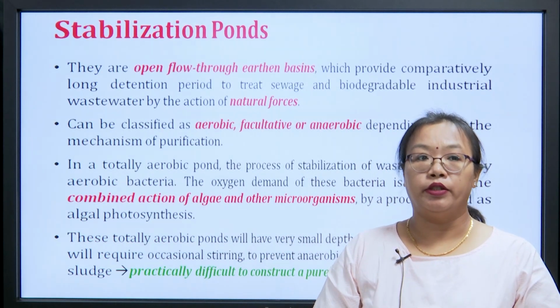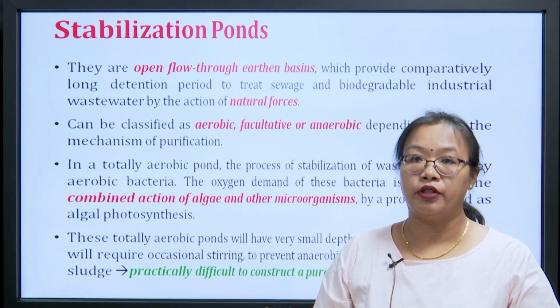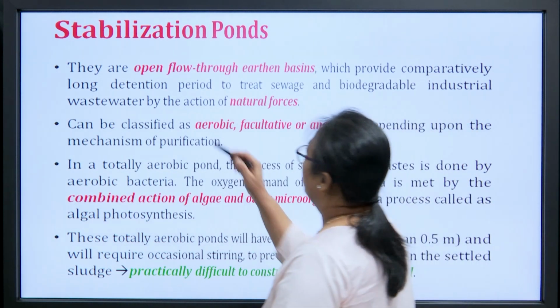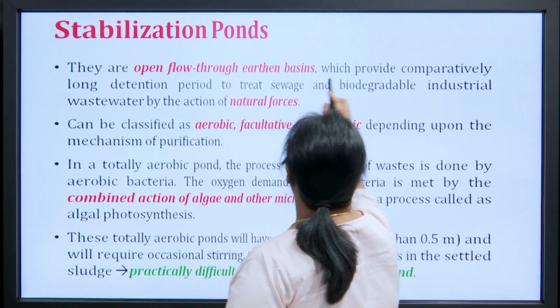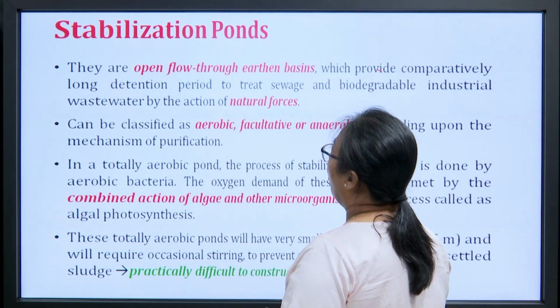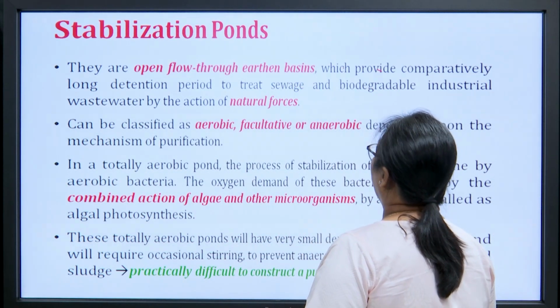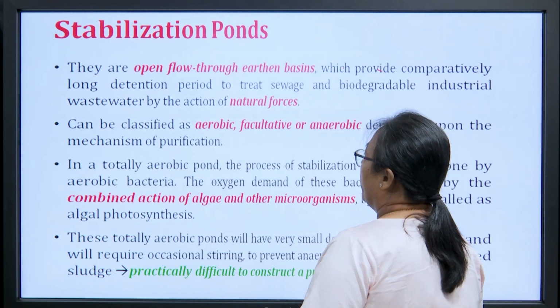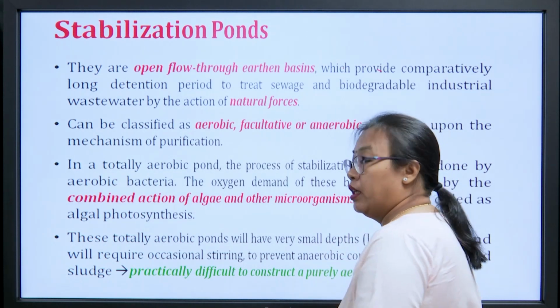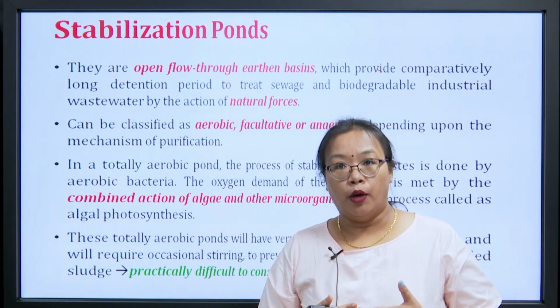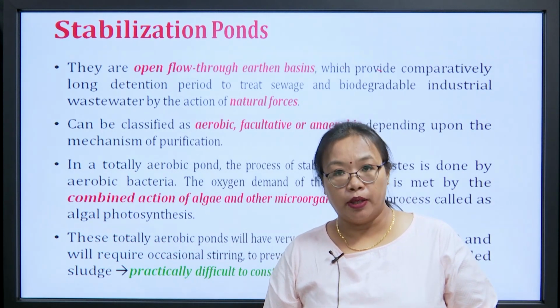So, what are stabilization ponds? Stabilization ponds are open flow through earthen basins which provide comparatively long detention period to treat sewage and biodegradable wastewater by the action of natural forces. So, in very simple terms, what are stabilization ponds?